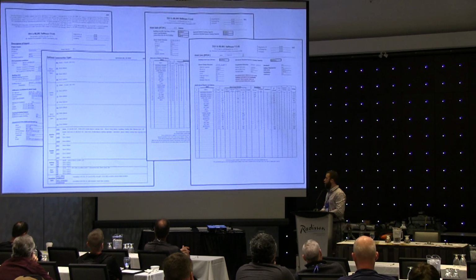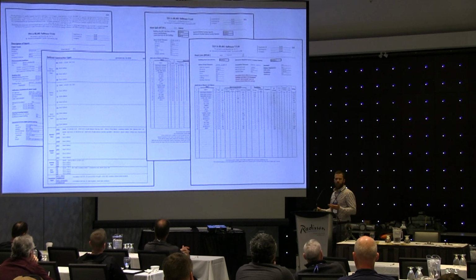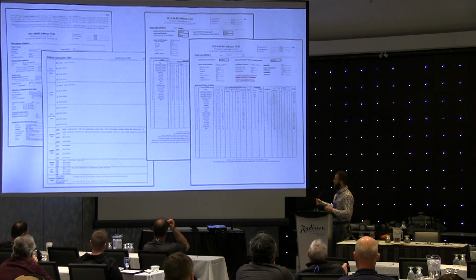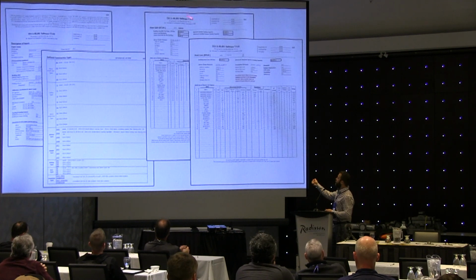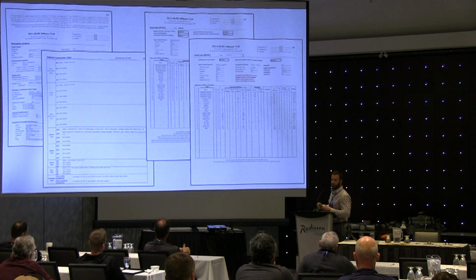One last little overlook at the results sheet. Does anybody have any questions about those? I hope you're somewhat familiar with how it might look, right? This is about the building, the environment, the mechanical systems in the building. This is about the envelope of the building, the walls, ceilings, floors, foundations, windows, doors, like the actual construction. Page 3 is heat loss, page 4 is heat gain. And if you're looking at a block load, page 3 and 4 are combined into one because you don't have the individual rooms listed out there.